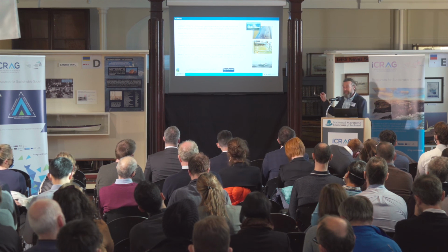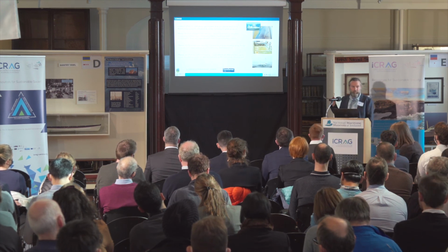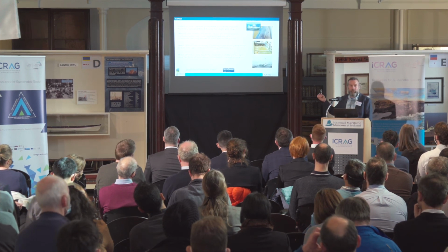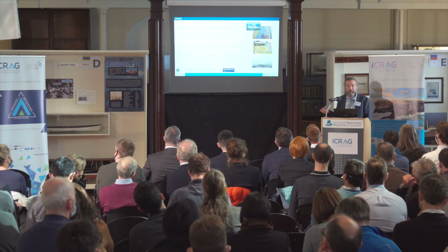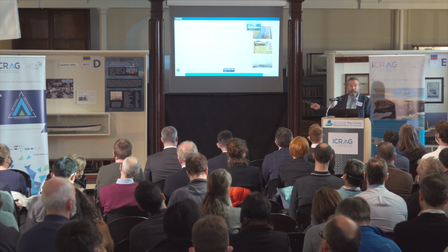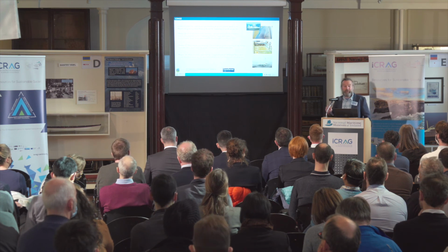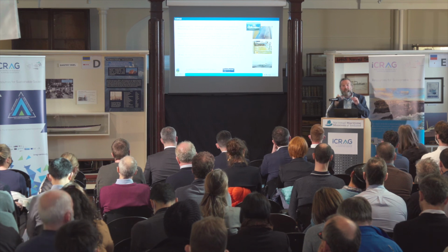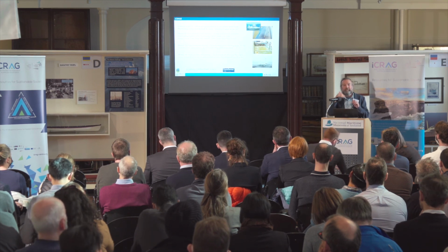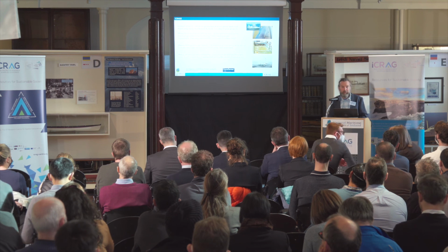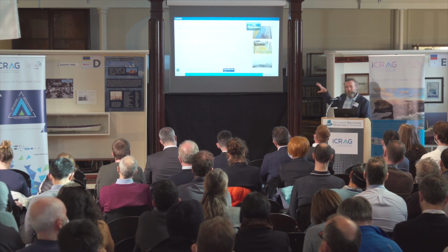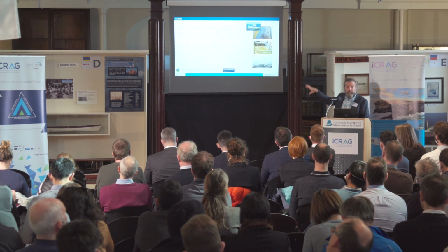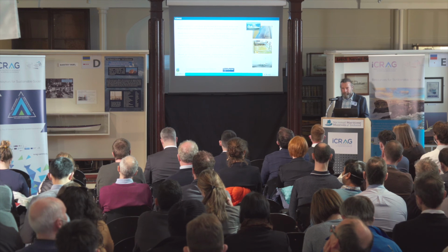So there are limitations in body wave. If this could record reflected signals as well as hydrophones, this would have been developed a long time ago, but they don't, because we're measuring longitudinal strain, whereas a reflection survey would be measuring a vertically travelling body wave. So that's why. But for surface wave, interface wave determination, it's a perfect tool for that. So. Thank you.